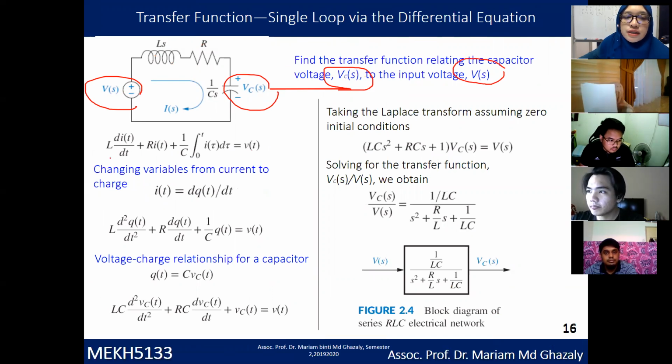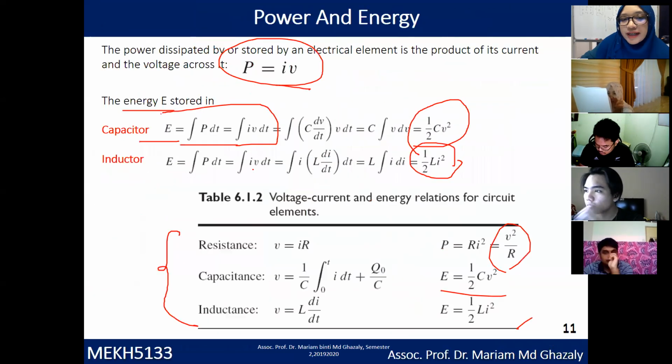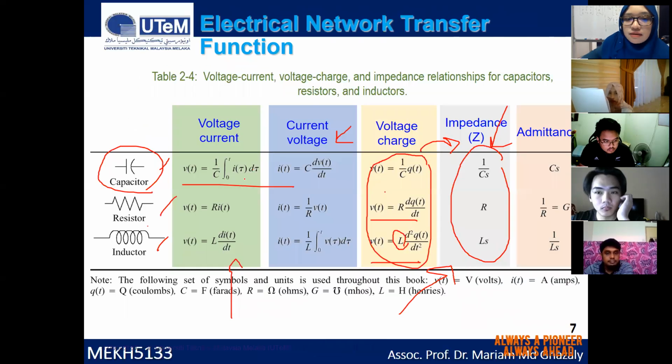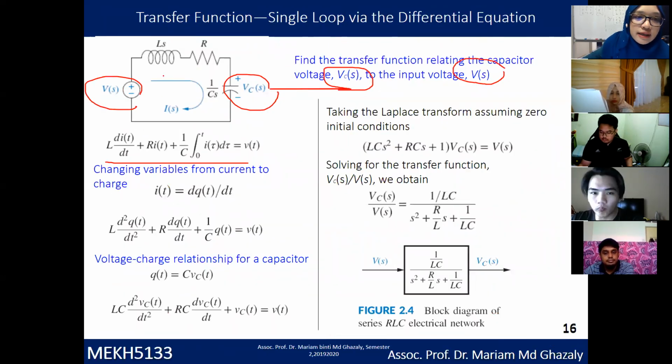Let's do the equation, using this in terms of voltage and current source. So it means that Vc(t) equals 1 over C integral of i(tau) d tau. Let's look at the equation. We have Vs in terms of the time domain. You write it out as L di over dt plus R i(t) plus 1 over C integral of i(tau) d tau. So you get Vs(t), the first equation.